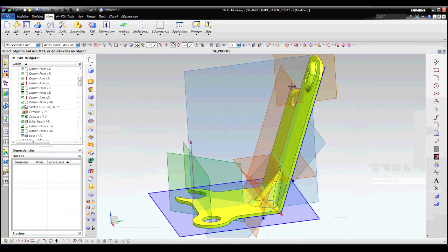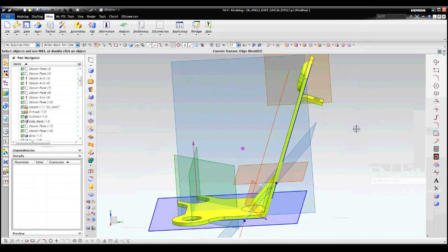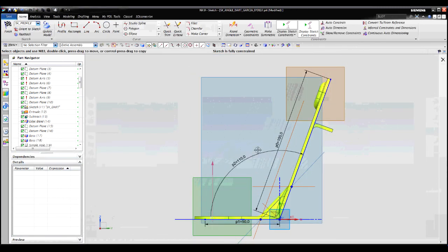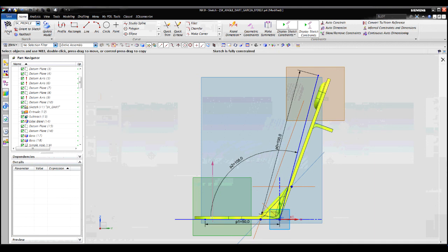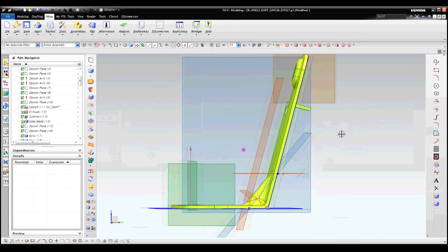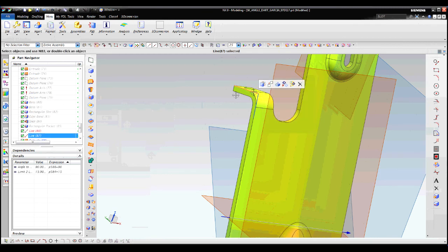Notice that there is a sketch here, and there is also a profile of this tab in the back. The sketch is with the profile, and the tab is being used with associative lines. And if I select the sketch that I use for the profile and double click on the angle and modify the angle, I want you to notice how the tab here will follow through when I finish the sketch. So it changes the angle as well, so it rotates, and it is because of the associativity of those two lines right here to the solid that we have here.